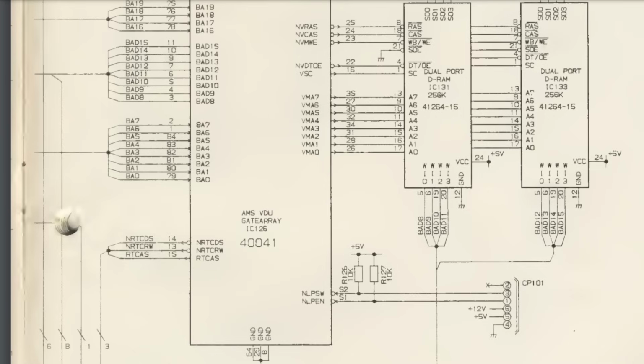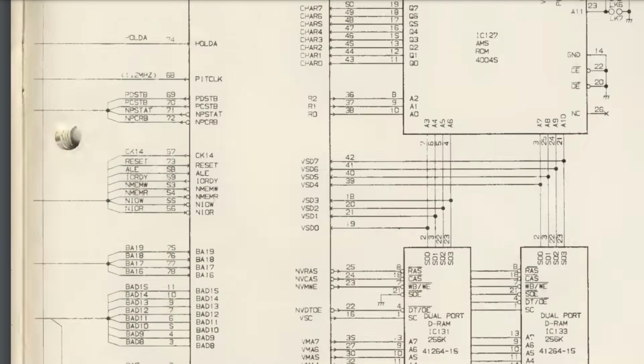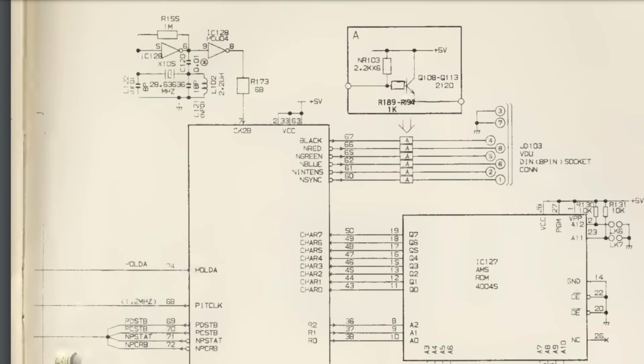Now that's not as bad as it sounds. I did some calculations, and in the 320x200 mode I think it works out to about 1 pixel's worth. That's 1 CPU cycle. So probably we're going to be able to set up an interrupt that'll get some code running on the CPU at the same place every frame within 1 pixel. So it's going to jitter about by just that much.